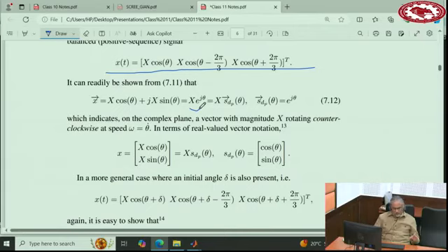It may sound a little complicated at the beginning, but as you go on, you will see how much they will help with the analysis and design of the 3-phase systems. So this e to the j theta, which is cosine of theta plus j sine of theta, I'm going to call it SDP. D for direct, P for positive of theta.